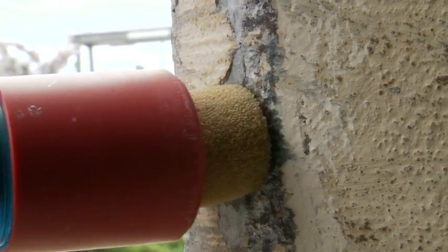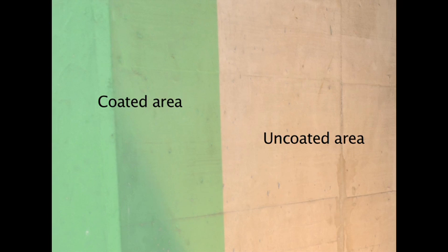If possible, areas with largely varying potential should be chosen. If there is no alteration of the potential, or if the shift of the potential can be compensated by a correction, for example plus or minus 50 millivolts, then a measurement can be made directly on the coating. If not, then the coating must be removed before making the measurement.